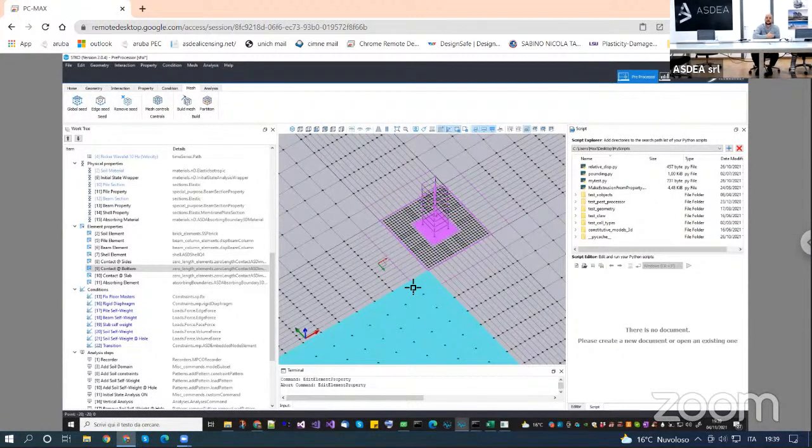But the problem is that the entries in a tangent matrix do not always have the meaning of a stiffness. Only in the elastic case are the entries of the tangent matrix the elastic constants. But in a nonlinear case, they are just derivatives, so they can be negative, for example.